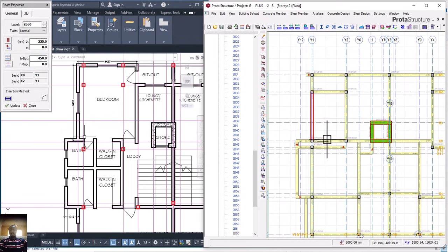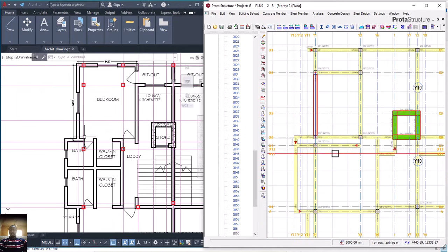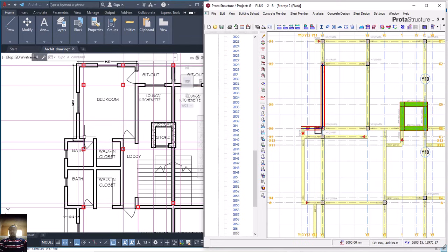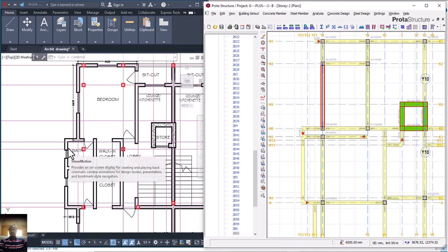So now, what's happening here? We can see that in this place we have this projection here. Or if we want, we can leave this one here like this, because it's still inside. Can you see now? It's still inside. We can still leave it and have a cantilever beam around here. Only this one we are going to remove, and put a column on this edge, isn't it?